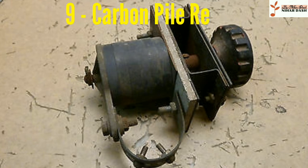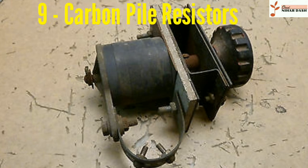Carbon pile resistor. A carbon pile resistor is made of a stack of carbon discs compressed between two metal contact plates. Adjusting the clamping pressure changes the resistance between the plates. These resistors are used when an adjustable load is required, for example in testing automotive batteries or radio transmitters. A carbon pile resistor can also be used as a speed control for small motors and household appliances, sewing machines, handheld mixers, with ratings up to a few hundred watts.